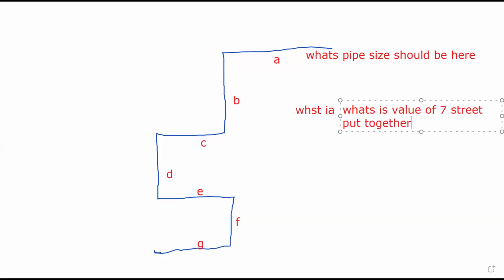So what do you do? If I'm correct, we get 7 times 0.69. That's just the value, 4.83. I go to the chart, 4.83 at 5%. What is the pipe size? 4.83 is as good as 5. 100 mm diameter. Thank you, sir. So do you understand it now? Yes, I understand. I'm clarified now.